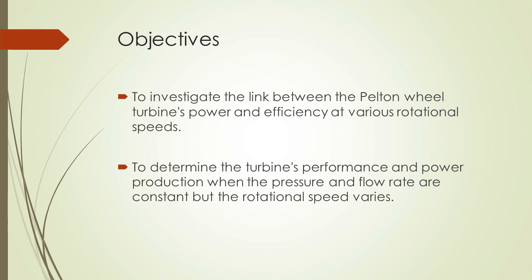The objective is to investigate the link between the Pelton wheel turbine's power and efficiency at various rotational speeds. Another one is to determine the turbine's performance and power production when the pressure and flow rate are constant but the rotational speed varies.